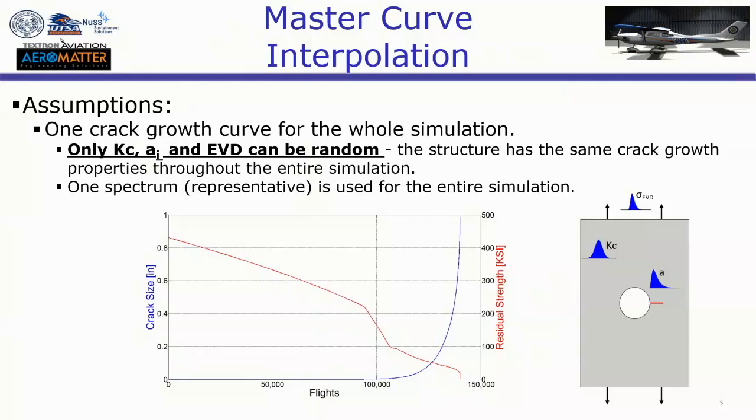The other assumption is that only one spectrum is representative for the entire simulation. So you generate one set of spectrum and you use that one to grow your cracks and to compute your EVD. So these are the assumptions that we have on the master curve.